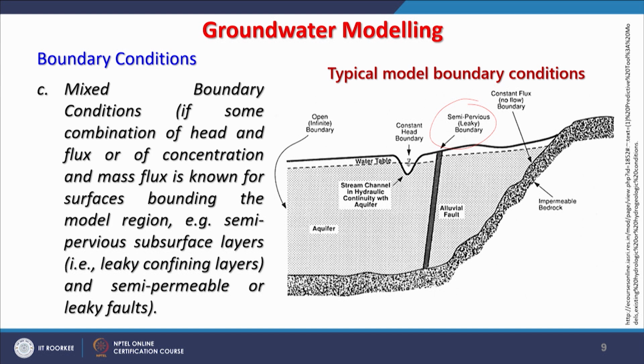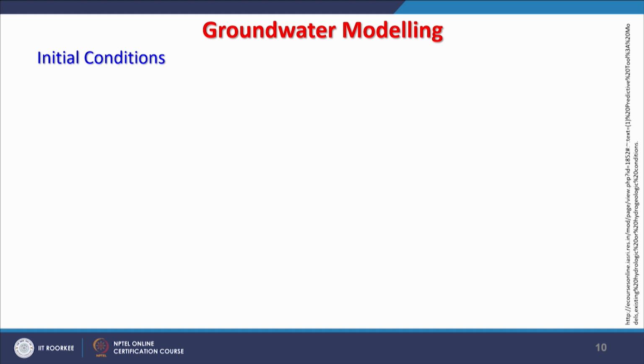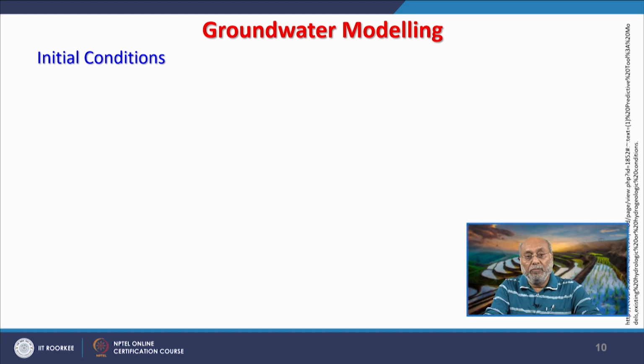I said that in the Indo-Gangetic plain these kinds of faults are very common. A lot of work has been done, or is being done, extensively to find out these faults. Generally, people think that in alluvium the faults might not be there, but there are many faults, and they may create boundary conditions if there is some impervious layer in between in groundwater modeling, or they may create hindrance in case of groundwater flow.